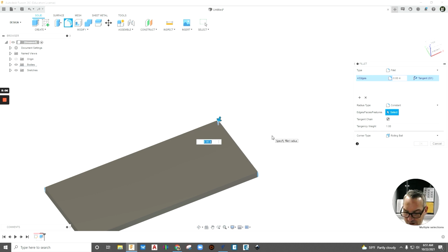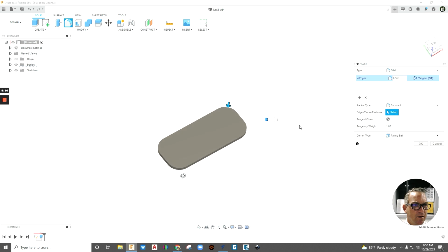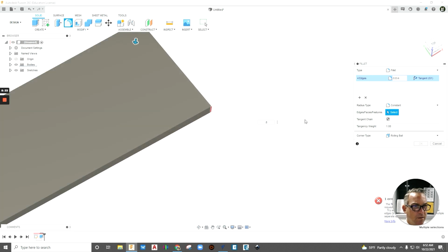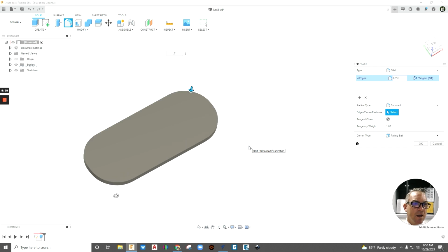And we can put in as the distance, the radius value, let's try 0.5. And there we go. Now I like 0.5, you may not like 0.5. You could make it less if you want, so let's just see what 0.2 looks like. See, not quite as rounded. Or what about 0.8? It doesn't like 0.8, does it? Is that right? Hold on, 0.7. There we go. 0.8 was too much. 0.7, you could see if you like that.